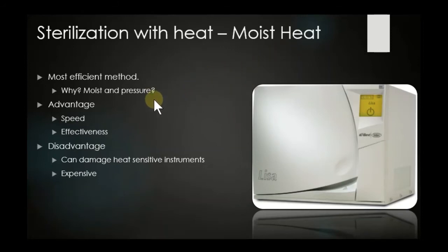So when we apply pressure on the water and then we raise the temperature, the boiling point, as we said, will be raised, so the stored energy within the generated steam will be higher. Once the steam comes in contact with the instrument, it will immediately release all this stored energy, and this will be better for instrument sterilization.